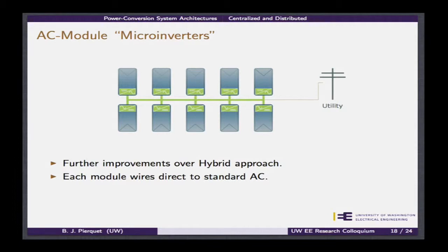If you were to do that in a DC system, you would still have high voltage DC floating around, and that becomes a big issue. This was a very large issue in the beginning for firefighters in different areas, because if you're trying to put out the fire on a home and it's sunny out, then you're going to have live voltage there, and you can't get the voltage out from each module. So ultimately the initial method was to put large, heavy, dark blankets over the top of the array to de-energize it during the day so you can actually do something with it.